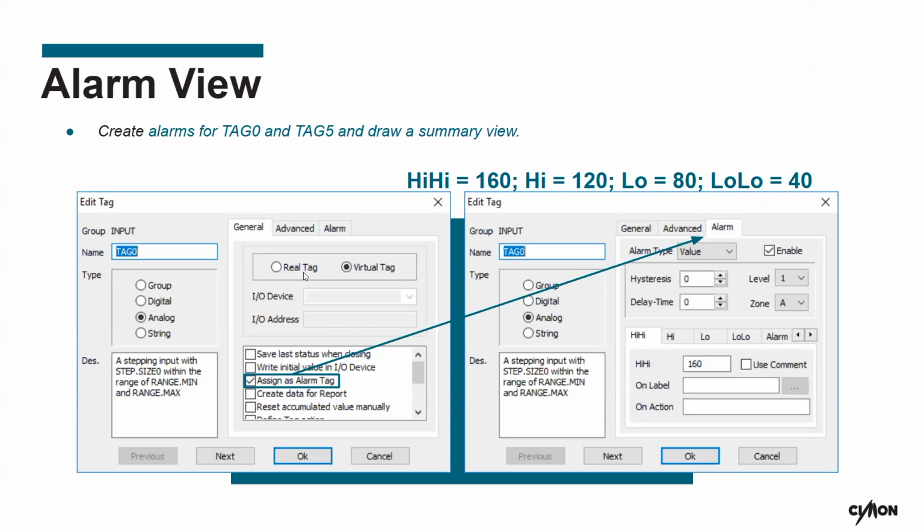I mentioned this on Tuesday, I believe, with SMTP. So we do have SMTP in the SCADA software as well. For those that were not here, you can utilize SMTP to send text messages, because certain phone carriers, like Verizon, have a domain that you can put at the end of your phone number that treats it as an email, but then sends you a text notification. Let me see if I can get an example going here.